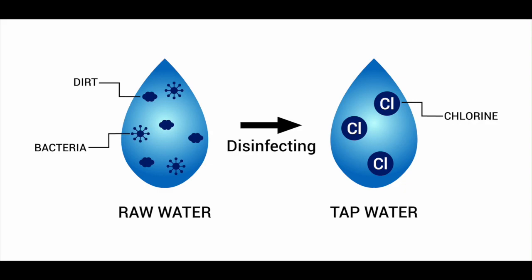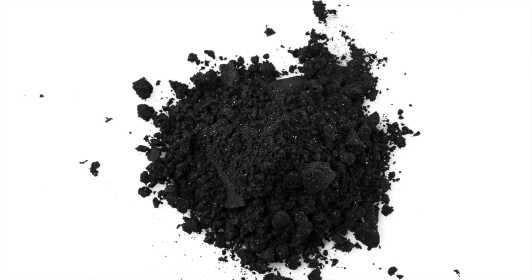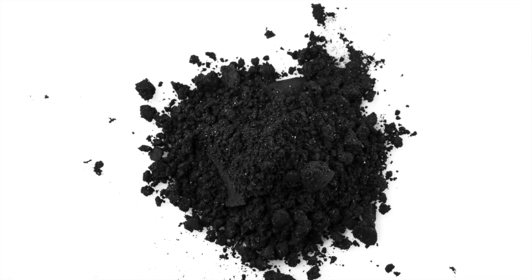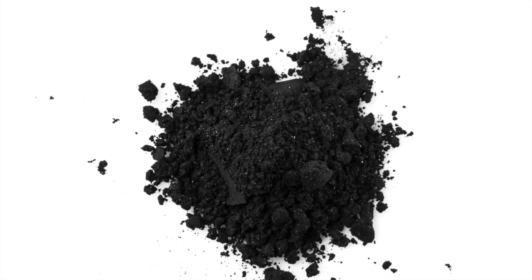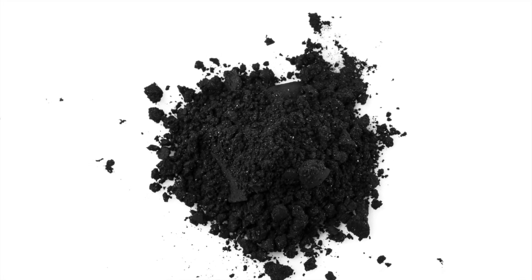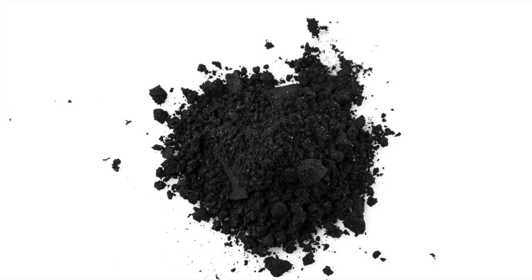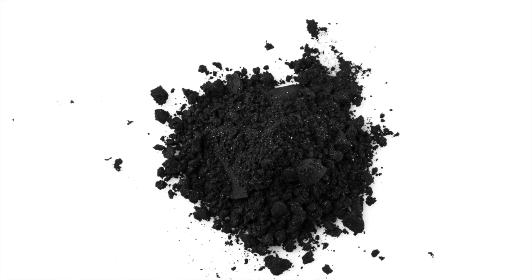Municipal water supplies usually use chlorine at concentrations between 1 ppm and 2 ppm to combat bacteria. If municipal water is used to grow fish, residual chlorine must be removed through either aeration or chemical treatments, such as sodium thiosulfate or activated charcoal. Concentrations as low as 0.02 ppm can still stress fish.